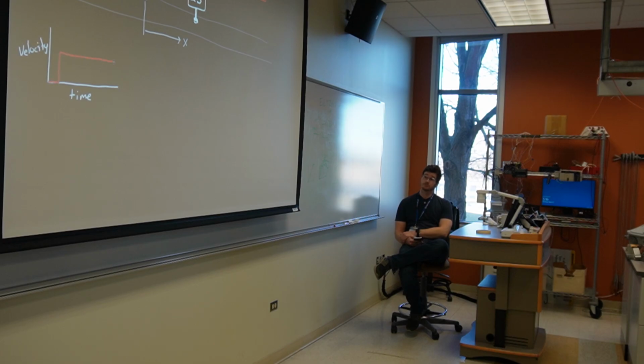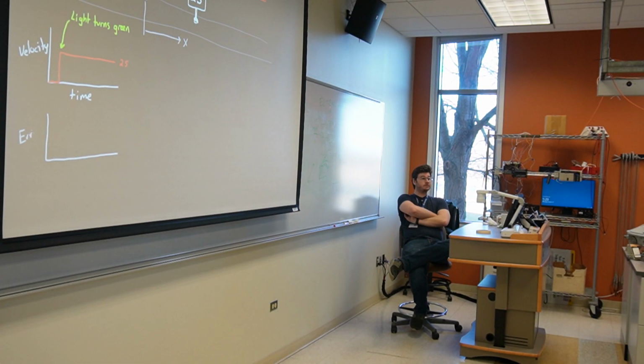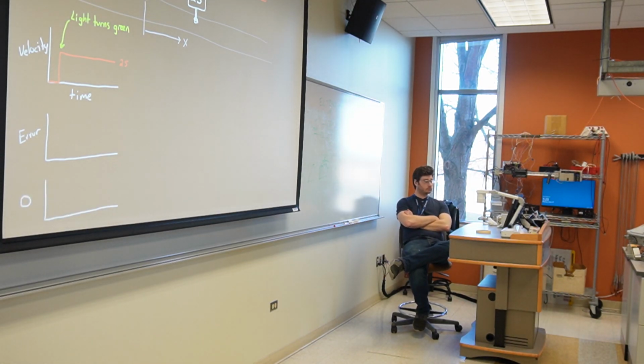Here's what happens. Initially, you're commanding 0 miles per hour. And once the light turns green, your reference signal steps up to 25 miles per hour. At this point, you have an error of 25 miles per hour. And this is a large error, so you apply a large change in the gas pedal proportional to that error, and you press the pedal fairly fast because of that.